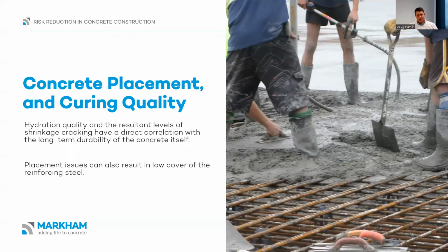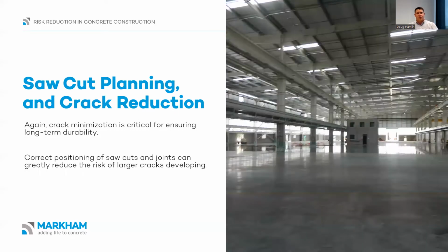Now, just on that, it's on the cover concrete. Its main purpose is to protect that reinforcing steel from deterioration or from rusting, which obviously leads to spalling, that type of thing. So if that cover concrete is compromised and it's not remediated, that can lead to that long-term or shortened service life, if you like, of the concrete. Should move on to the next one.